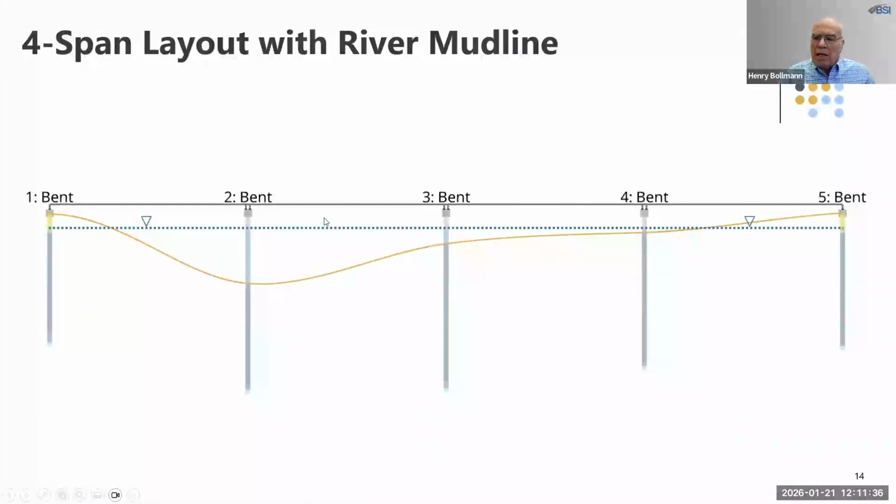And the bridge we're going to look at is a 4-span bridge that basically looks like this. And this is a drawing that Wilmer made for us here in the office. And basically it shows end bent 1, and then over here to the right, it shows the bent 1 and end bent 1 over here, and the other piers. What else do we see? We see a water table. We see that all these bents have 2 rows of bearings. That's because these are simple span beams, simple span beams, simple span beams. So you can see that.